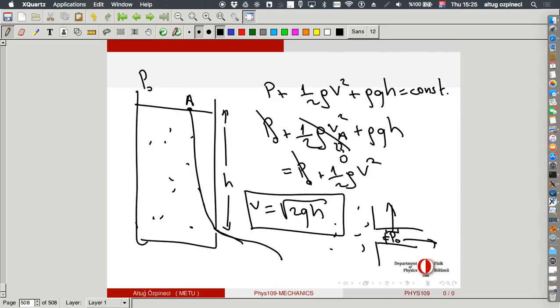Now the next. Through a small dust or a piece of something that can move with the fluid, we throw it at a velocity 0. Would its velocity when it's exiting be 0 plus that? Well, we made several assumptions here. First of all, this point is not moving. So if you put some speck over there, it will take an infinitely long amount of time to reach this point.